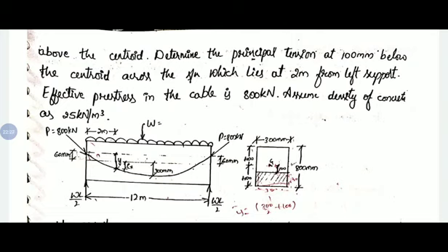So in 400 we need to consider 100 mm below the centroidal axis. That means from bottom we need to consider 300 mm height, that area for calculation of stress. At that particular level we need to find out the tension stress. So the area of the shaded or hatched portion will be 300 by 300.